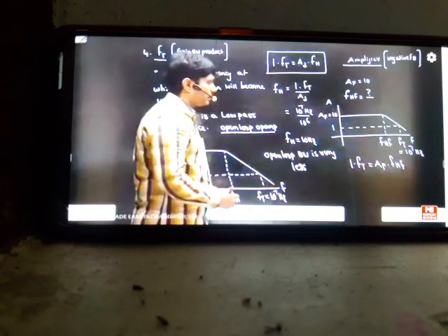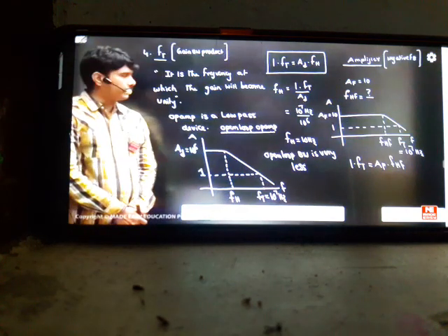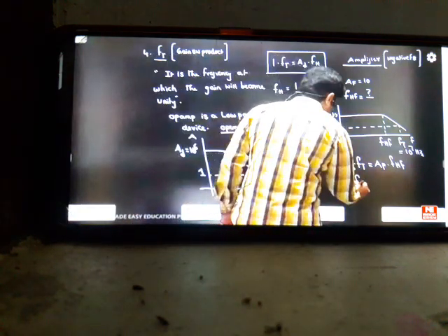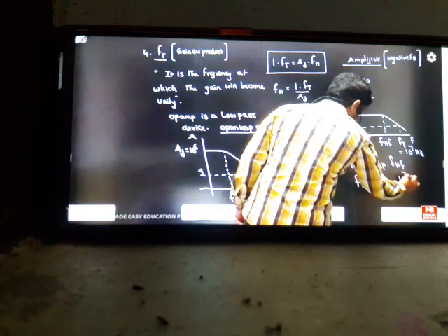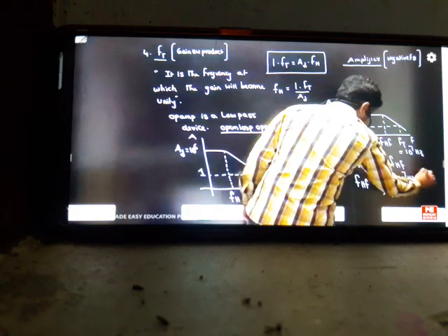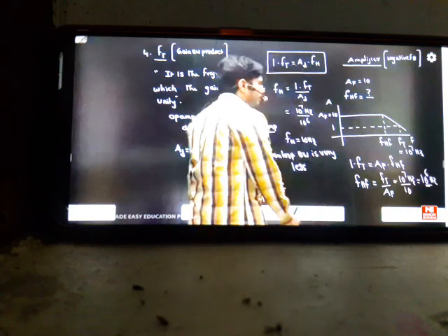What that F represents is the feedback bandwidth. So the formula here is FH of F will become FT by AF. It is 10 power 7 Hz divided by 10. It is nothing but 10 power 6 Hz. So can you see that the bandwidth has been drastically increased?